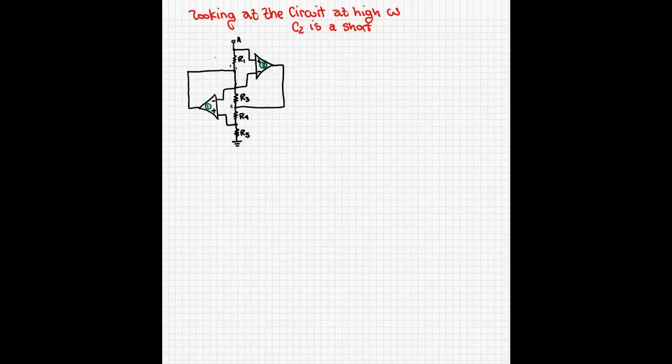Okay, so a few things to note. Op-amp 2 is going to try to make its positive terminal equal to its negative terminal. How can it do that? Well, one way it could do that is by increasing the voltage at node 2. Once it does that, you're going to see there's going to be a drop at this point, which is going to make V negative equal to V positive equal to VA. So you're going to have VA right here. Since these two nodes are at the same potential, there's no current going through R1, correct? So the first thing is there's no current going through R1.